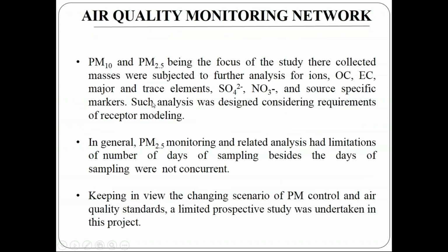And for PM 2.5 and 10 being focused on the study, their collected masses were subject to further analysis, like your EC, major trace elements, conductivity, sulfur dioxide, nitrogen dioxide, SOx, NOx, etc. This should be designed considering all those receptor modeling. Means we have to fix the purpose or objective, what parameters are to be monitored for modeling or for our requirement. In general, PM 2.5 monitoring and related analysis had limitations of number of days of sampling, besides days of sampling were not concurrent or regular.